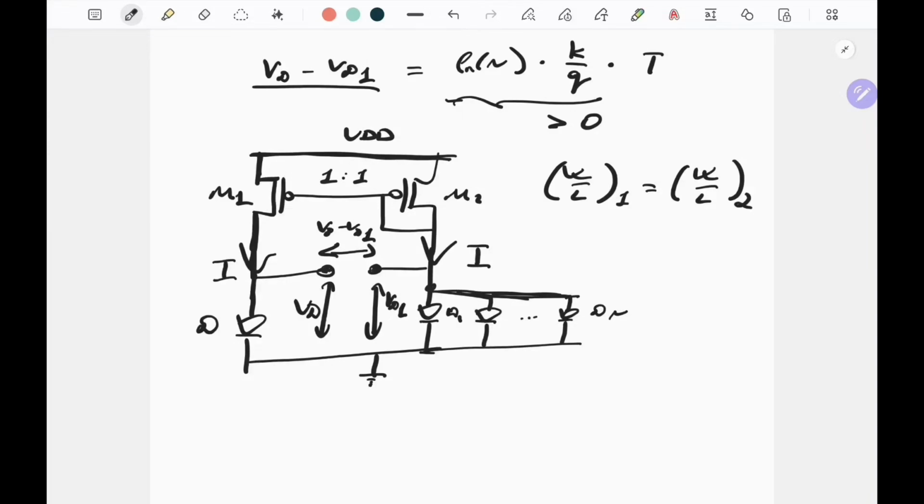Please notice that in my previous video I put a diode connection on M1, here I put it instead on M2. For this particular circuit, it is not important which of these transistors would be in diode configuration. But for the next circuits that we are going to build, it turns out to be important. So I choose to start with diode configuration on M2.